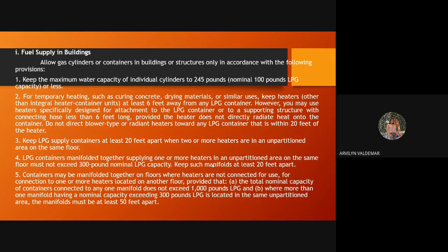Next is LPG containers manifolded together supplying one or more heaters in an unpartitioned area on the same floor must not exceed 300-pound nominal LPG capacity. Keep such manifolds at least 20 feet apart.